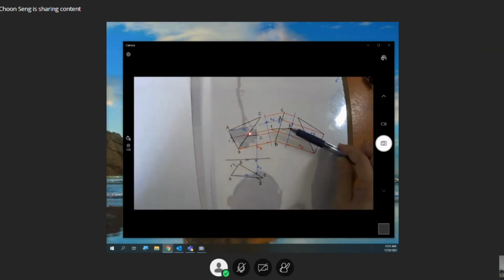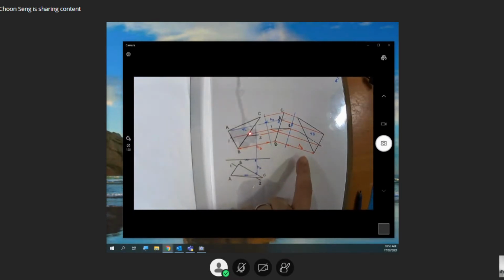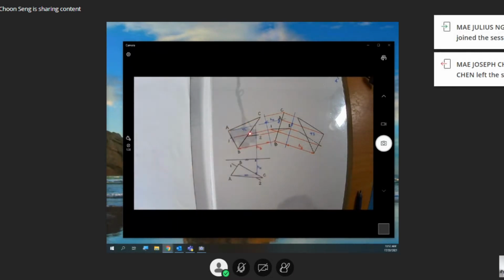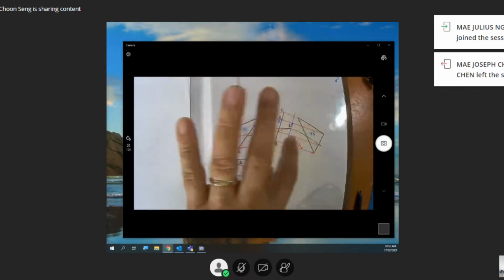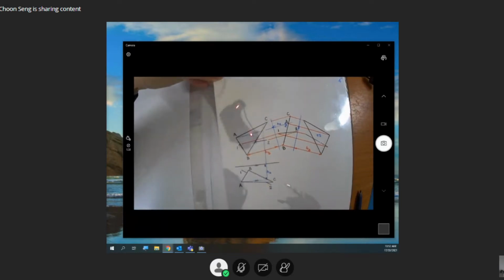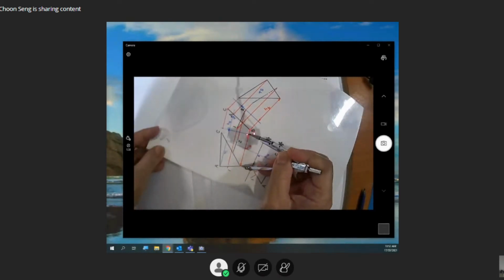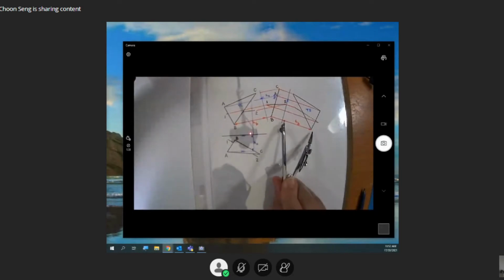So place your eyes here, third angle. Place your eyes here and you draw backwards. The height, you notice I just indicate one point. Once you know where I get this line or this height, you should be able to follow point A and point C. Follow because I do not want to clutter it. Now, for point B, this is your vertical height from your previous view. Transfer.